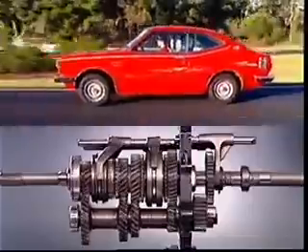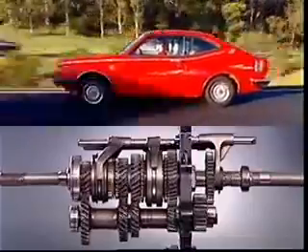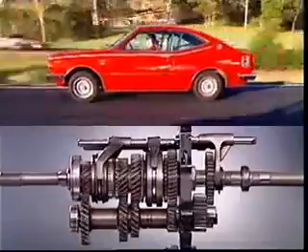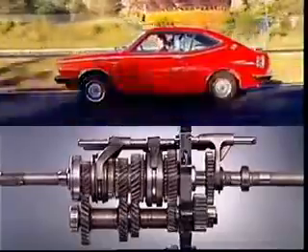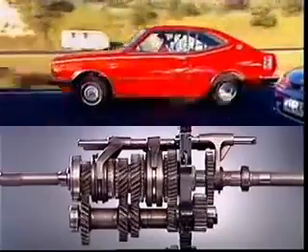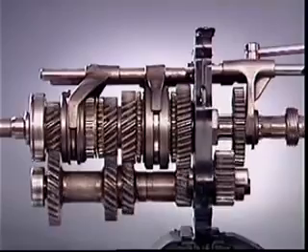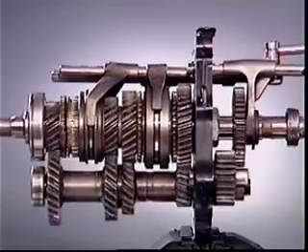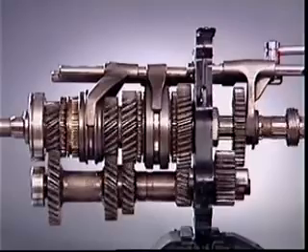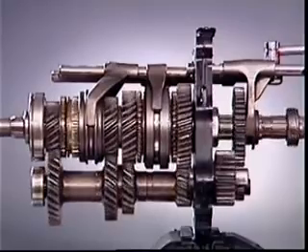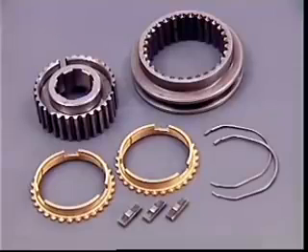With the vehicle in motion, these gears will be turning at different speeds in relation to the main shaft and to the engagement sleeve, which is locked to the main shaft by the spline. When changing gear, their speeds must be synchronized so that the engagement sleeve can move smoothly into engagement. A balk ring type of synchromesh unit is commonly used to synchronize the speeds of two gears before engagement.